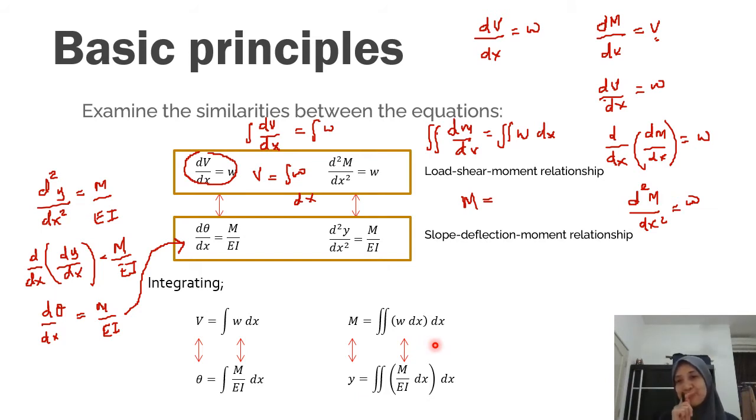That's the relation. Just to recall, the moment is the single integration of your shear. That's why the area under the graph of your shear force diagram is your moment, because it's the first integration of shear or the double integration of the load.